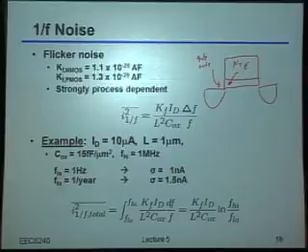Okay. So there were two different things that were said. One was that it increases Cox, and the other was that it affects the threshold. Say that again? Oh, decreases. Well, it turns out that it doesn't actually modify the oxide capacitance very much, because it's really just one electron, so it can't really screen much charge on the other side in terms of really acting like a capacitor plate. But indeed, what it actually does is basically change the threshold voltage.